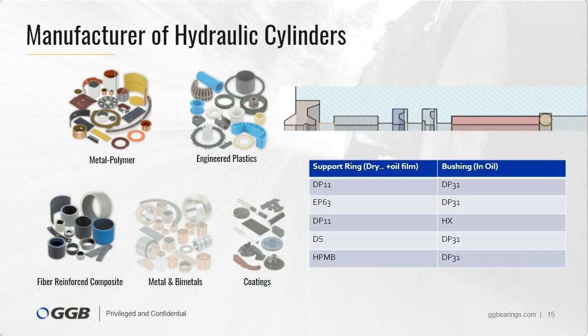So those are typically where we look when we have very harsh chemical environments or corrosive potential. We also provide metal polymer materials on bronze backings rather than steel, which a lot of customers that have to tolerate more corrosive or chemically intense environments prefer, because otherwise it is a familiar technology for them.